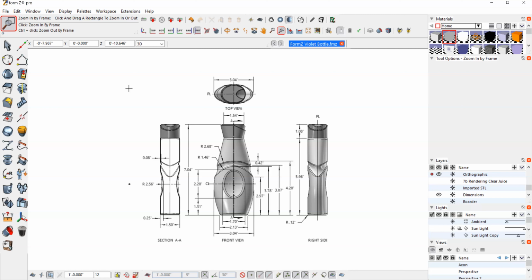What I do is I proportion my border to fit on a printable page. Quite often I'll print these on 11x17, fold it in half, and I can put that into a document for a presentation when I do face-to-face. So I like the 8.5 by 11 folded in half, 11x17. So I will take the 11x17 proportion and scale it up so it fits nicely around what I have detailed here in my specification drawing. And I keep a pretty even number. I scaled it up here and I made this one 21 inches by 14, I believe. It fit very nicely. And I'll bring that in.